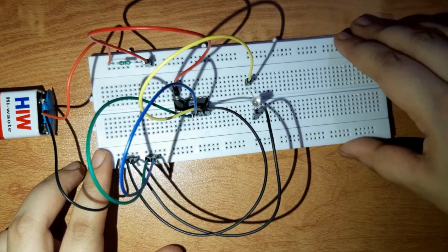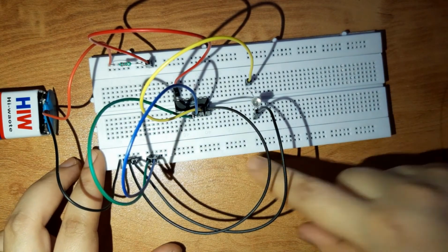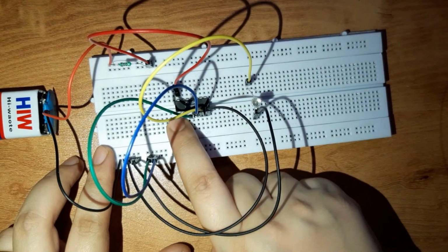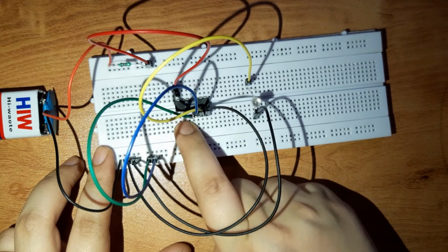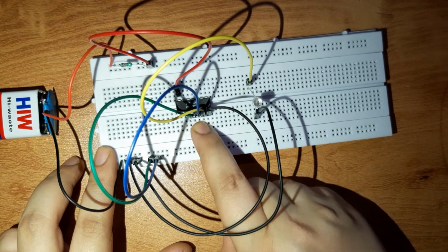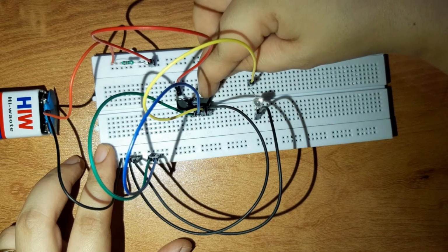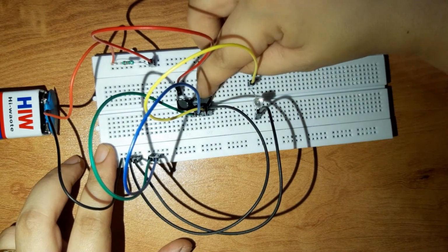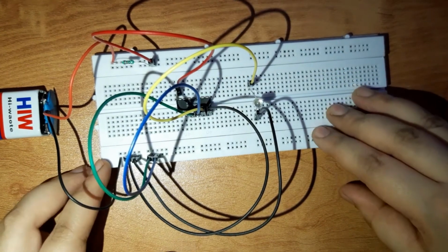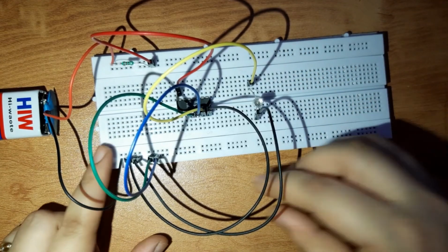So this is how the OR gate using the 7432 IC can be implemented. This IC 7432 gives you 4 different OR gates. You can use the first three pins where the first and second pins are inputs and the third pin is the output, then the fourth and fifth pins are inputs and the sixth pin is the output. Similarly on this side, the 8th pin is the output and the 9th and 10th pins are the inputs, and accordingly the last one. So this is how the gate is to be implemented.